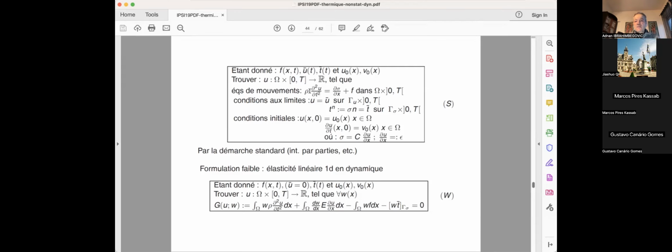And then, next to these boundary conditions, in other words, imposed displacement and imposed traction for the Dirichlet and Neumann boundary, respectively, you also have now to define the initial condition for your body. That is at the moment t equal to 0 when you start following the motion. You have to define what is the initial displacement u0 of x and what is the initial velocity v0 of x.